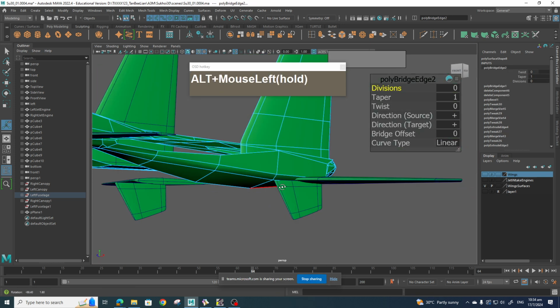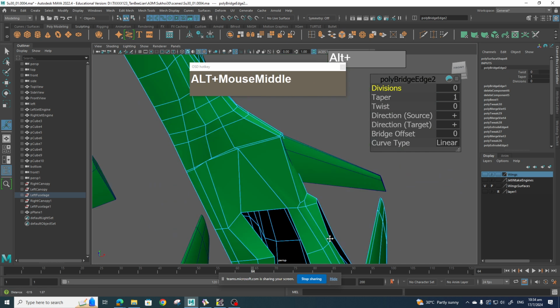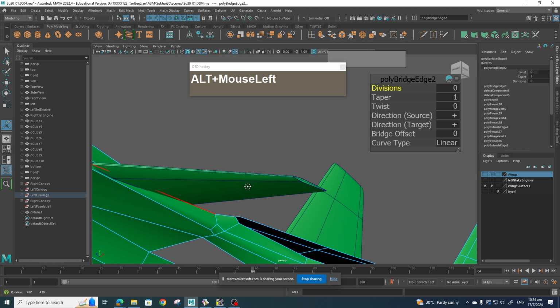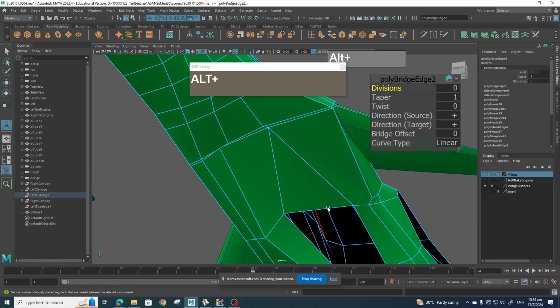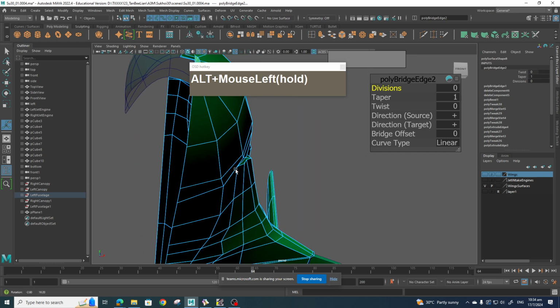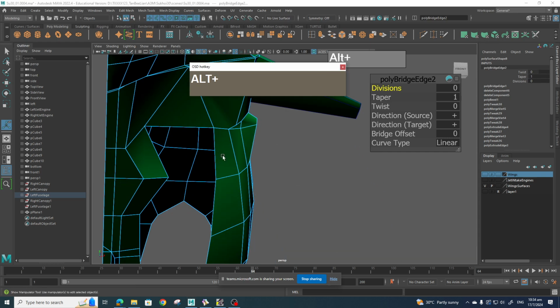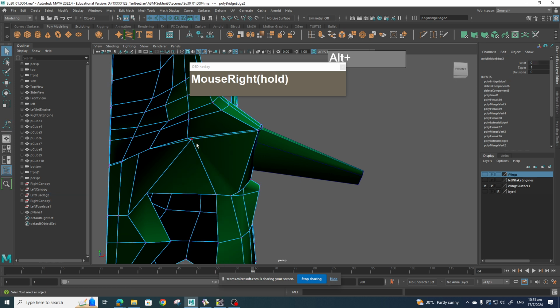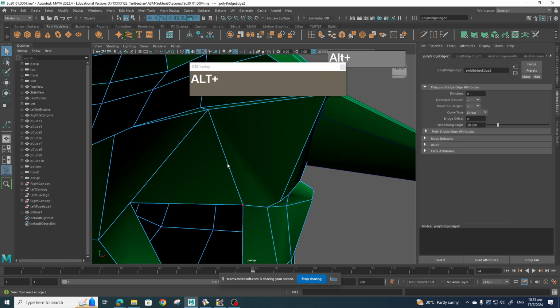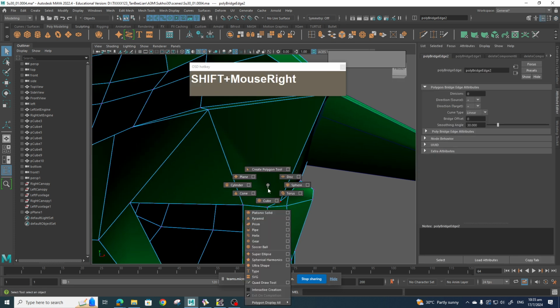Alright, so because we create a bevel, there's going to be some weird topology going on around here, so we're going to fix this over here. So okay, this one is four-sided, it's still alright, but this one, we will have to find a way to fix this. And since we have a triangular face here, I'm just gonna see what I can cut across here using a knife tool.